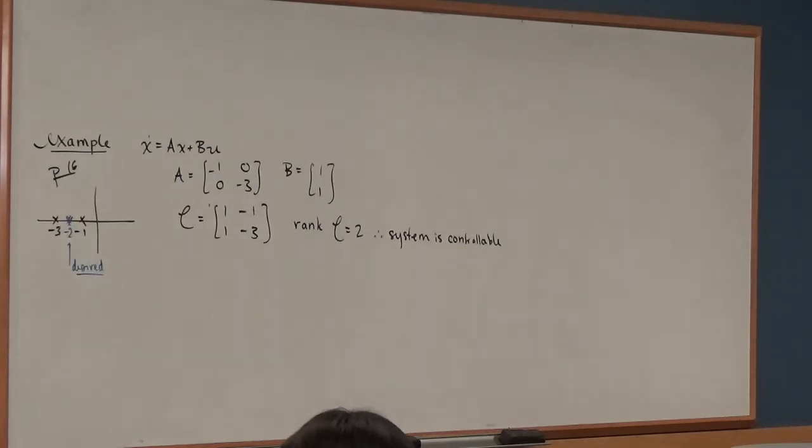Often when the system is small, you don't do that. Most of the time, I don't typically transform the system to controllable canonical form. It's more of a vehicle for proving the ability to place the eigenvalues anywhere you want than something that you would typically use computationally. I think the algorithms in MATLAB use this because they're doing it for general large matrices, so they want a canonical form to transform to, so they can always use the same canonical algorithm for pole placement or eigenvalue placement. But typically for small systems, we would just do it directly, like we did in that first motivating example.